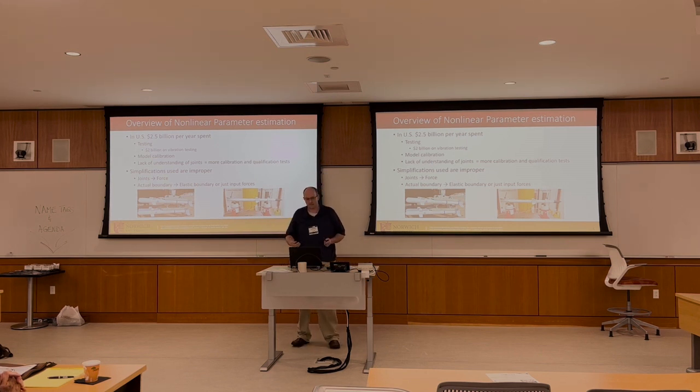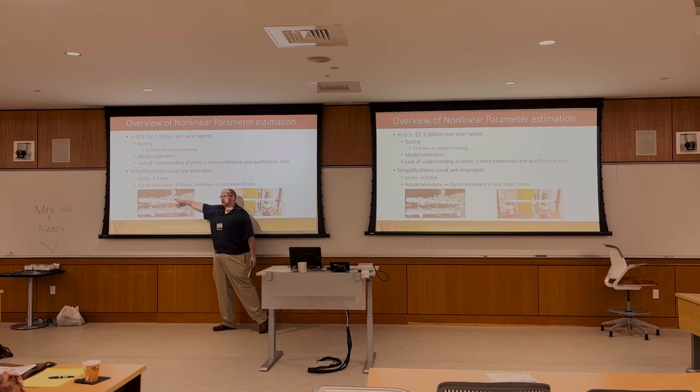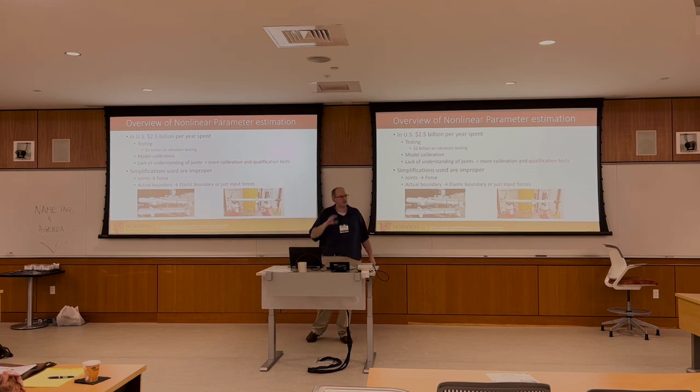That is actually different. Another part of this is the actual boundary condition. A lot of times we have this, and then we're saying these two shakers right here model it perfectly. If I'm able to exactly control it, it's exactly modeled correctly. That's not correct.